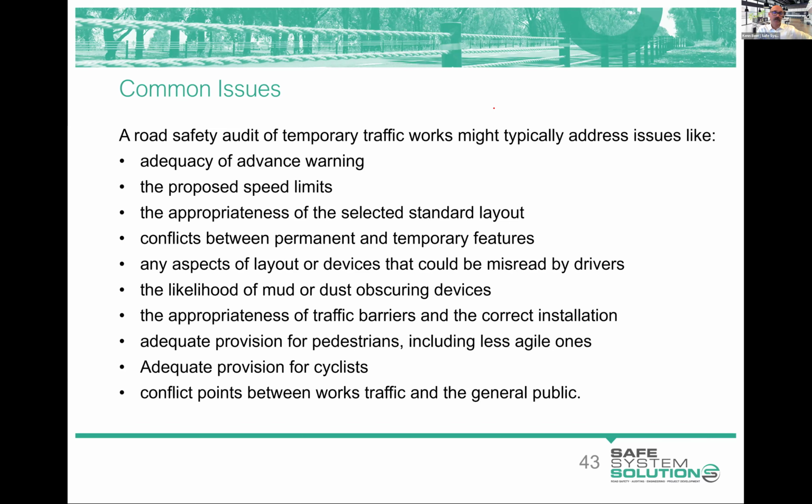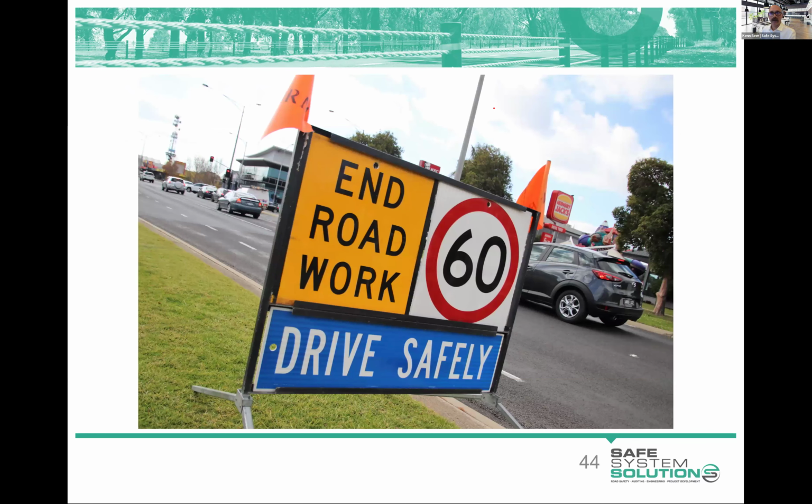One that unfortunately I keep seeing, if it's a water-filled barrier, does it actually have water in it? Otherwise, it's just a glorified witch's hat. So those are some things around barriers. And again, just make sure your team contains somebody who knows a bit about road safety barriers, temporary barrier systems. Pedestrians, cyclists we talked about, and conflict points between work traffic and the general public. So that's probably all I wanted to talk about for roadworks.